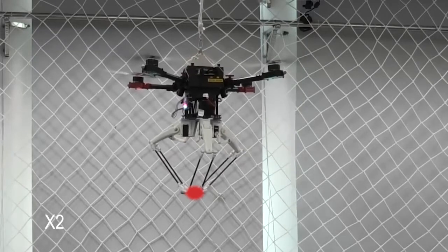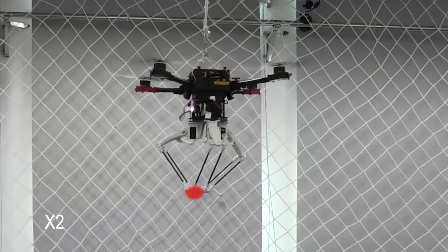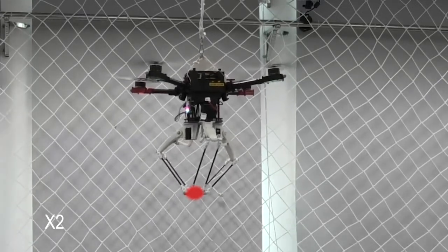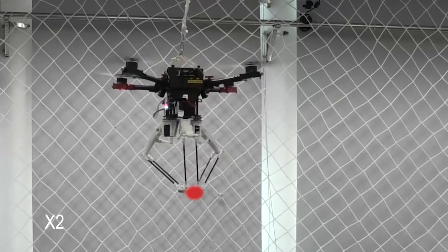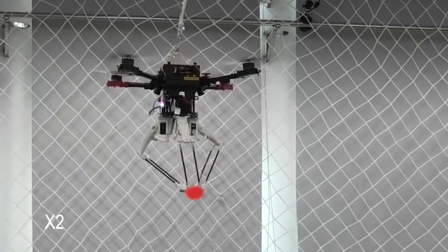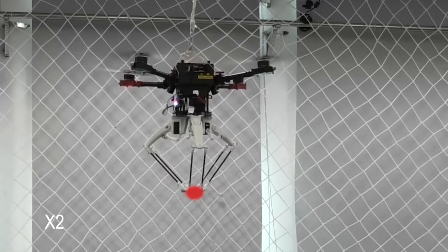The purpose of this experiment is to validate the PP mode of the proposed cooperative planner together with the flight controller. The control objective of this experiment is to stabilize the end-effector to a fixed position while the quadcopter is flying along a circle with radius of 6 cm.